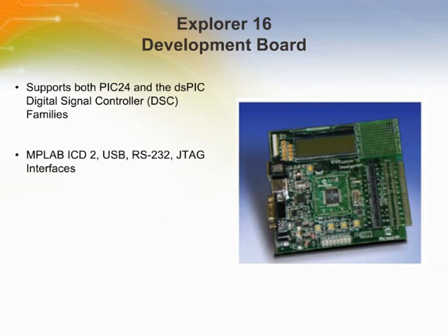The board includes the power supplies, buttons, switches, and displays that you would expect in a development board. It also includes a small prototyping area and a socket connector for use with the Microchip PICtail, plus daughter boards. At this time, 2 daughter cards are available to quickly enable the Explorer 16 board to connect with an SD MMC card or to connect to Ethernet through an ENC28J60.